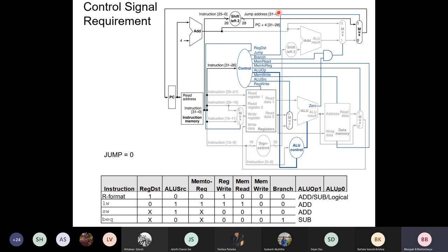So once you understand this overall layout of this processor and what happens, depending on the format of the instruction you know what kind of actions need to be executed sequentially. You know what sort of data path you need, and accordingly you select these control lines. This control line should achieve this kind of values depending on the corresponding instruction. So now the next objective would be to design this controller, which is essentially a combinational logic whose input is the instruction opcode and the function field. Outputs are these signals. Solving that truth table will give you the logic for the control unit.